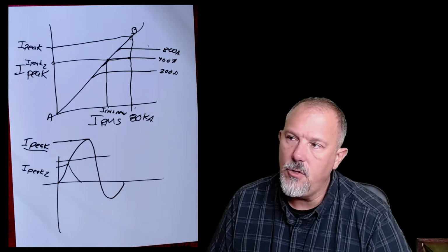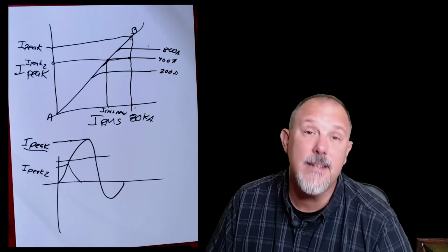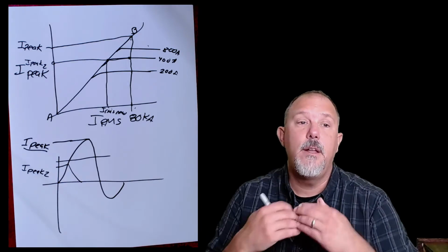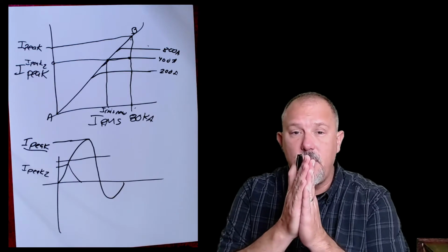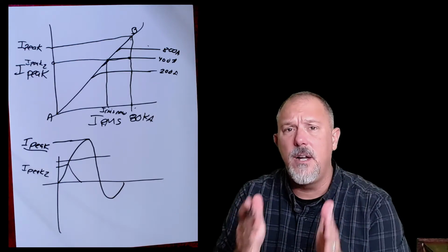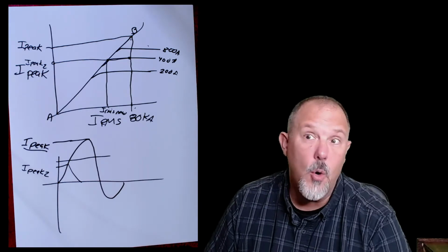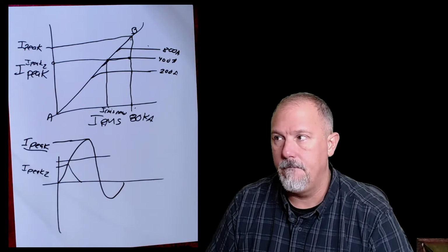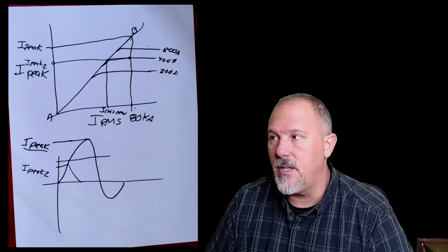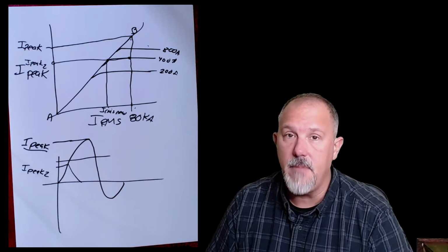So the question was, can you use up, over, and down for higher fault current reduction at equipment that is rated 5kA? And I would say sometimes. If you have a circuit breaker in there or any type of dynamic device that's also going to be trying to part its contacts under those fault currents, then you can't use the up, over, or up, over, and down method. It's going to be done via a test method. But 110.10 would recognize when it's permitted to use an up, over, and down method.